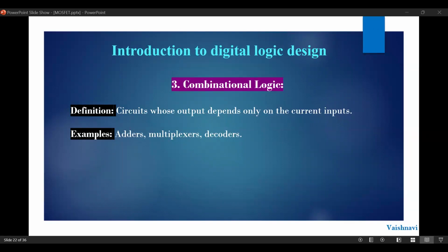How should I explain it? You know log to log. Okay, 4 to 1 mux. How many lines can you select in a 4 to 1 mux? You use 2 lines, select 2 lines. What happens in a demultiplexer? Demux means, let me tell you a simple thing: a multiplexer is an n to 1 multiplexer, and a demultiplexer means a 1 to n demultiplexer.